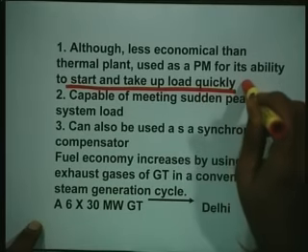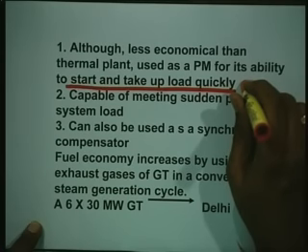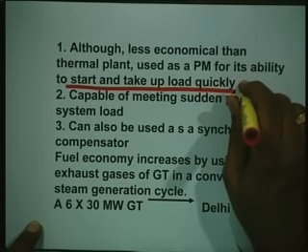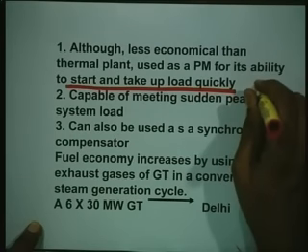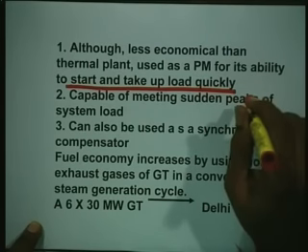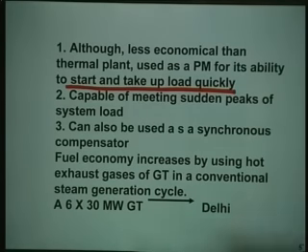So, gas turbine, which is very handy, the land per megawatt required is very small, and it is not that costly, and gestation period is not that high, 8 years or 10 years, and that is why gas turbines, though low efficiency, are preferable wherever you have to meet the peak load for short duration. Peak load means short duration. If it is for long duration, it becomes a normal load. How do you call it a peak load, right?